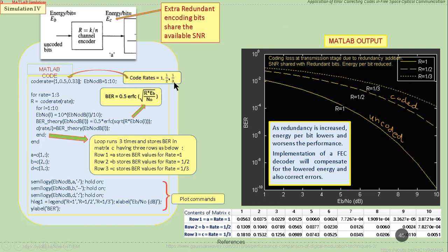And we have to pay for the bandwidth, and maybe we need to pay for the decoding implementation at the receiver, but this provides us with an error free solution. Now, without encoding we have this curve, and at say 6 dB SNR, the errors that are happening are such that in every 10,000 bits one error is expected.